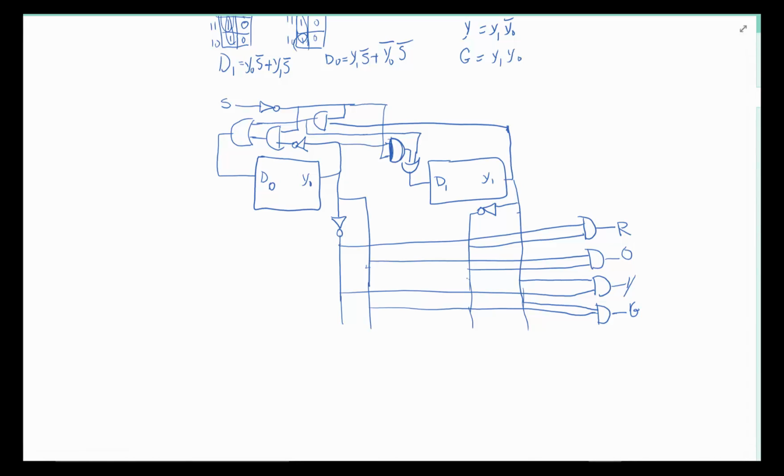All right, so you notice if you remember or if you watch the video about one-hot encoding, you see that this one has fewer flip-flops but has a lot more gates, and the other one had double the flip-flops but not as many gates. And depending on what you're designing, which of these is a better solution for you, that's the one you need to go with.